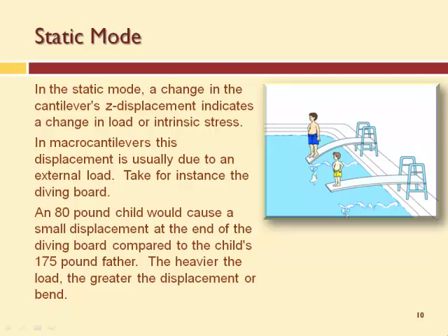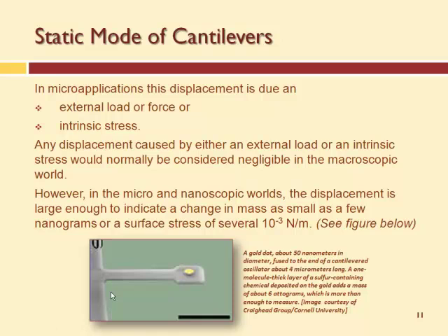That would be an example of using a cantilever in static mode. A lot of cantilevers in the micro world use the static mode of operation. pH sensors are done that way. You can use touch sensors, so you can look at forces on an actual microcantilever.